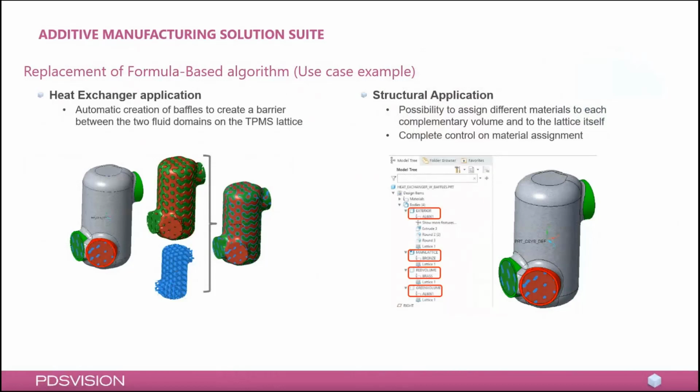And all of those you will get from the lattice generation automatically, and this enables you to make the heat exchanger so that you have a maximum amount of contact area in the shortest possible distance. And you will get each of the 3 volumes out of it as an outcome. So if you have any exotic applications where space is really the issue, this might be one of the solution drivers for that.